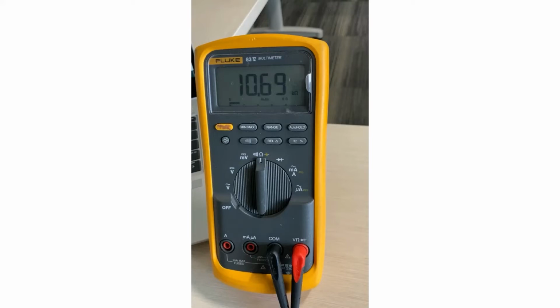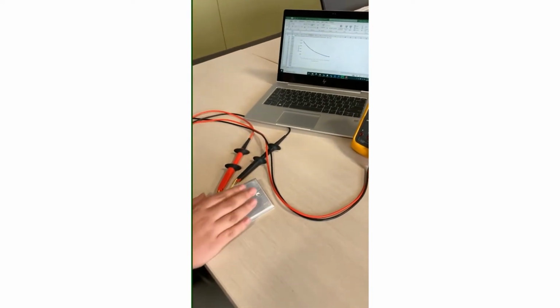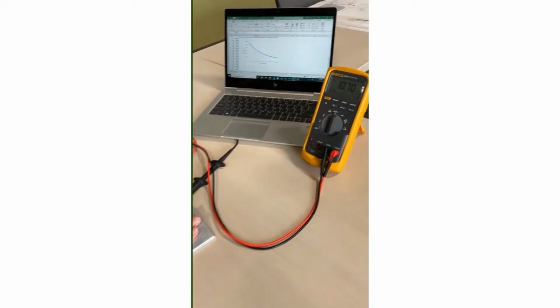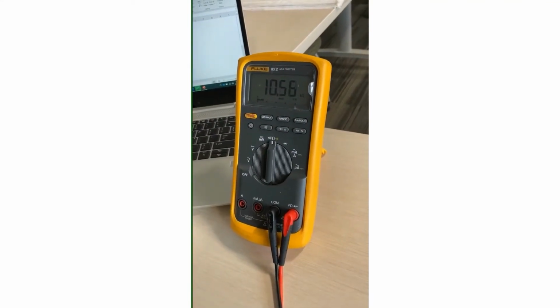To show the electrical property of resistance changing with a wall plate type thermistor, here, a student's connected a digital multimeter, making sure the leads are in the correct place to measure ohms. We can see the units are ready to measure kiloohms. And we can also see how the resistance changes as the temperature of the wall plate thermistor changes. Let's see what happens. As the student warms up the thermistor plate with his hand, the resistance goes down just like we saw in the temperature resistance chart on the last slide.